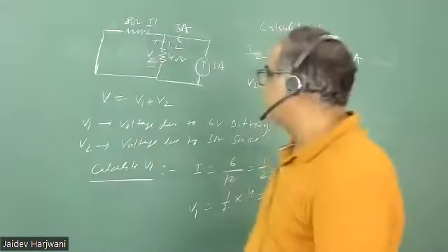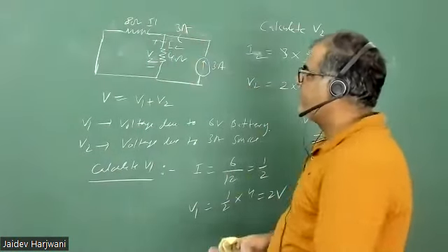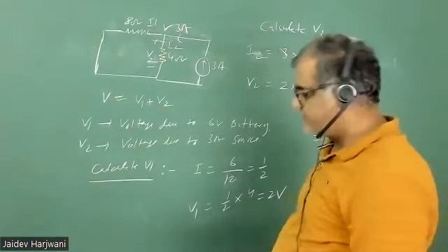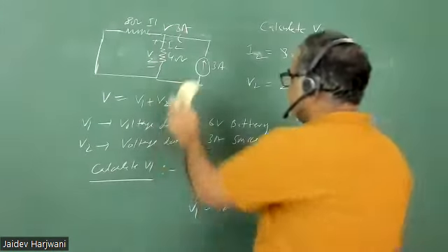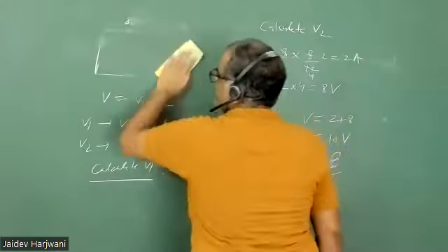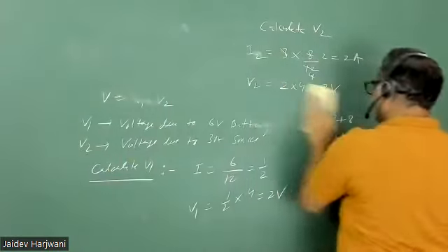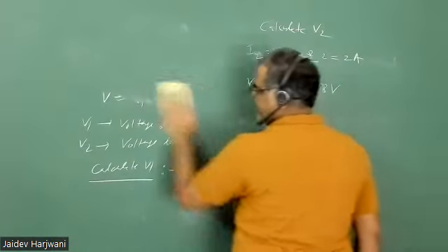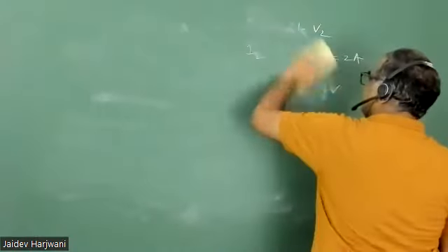Now, you can do the same question using nodal analysis. You want this voltage, so you say this voltage is V and do nodal analysis. You can solve the same thing. Whatever method you find comfortable, but I suggest you learn both methods, nodal analysis and the superposition principle, because that will help you a lot while dealing with circuits. Both techniques are equally important.